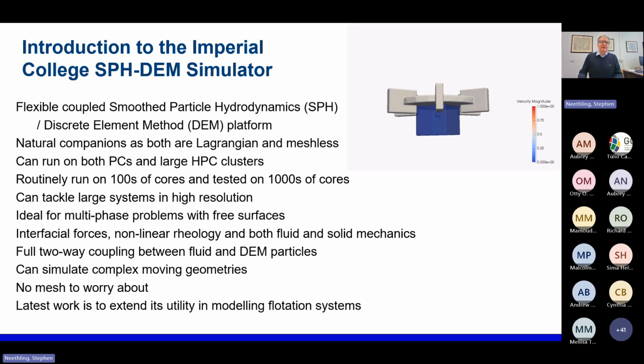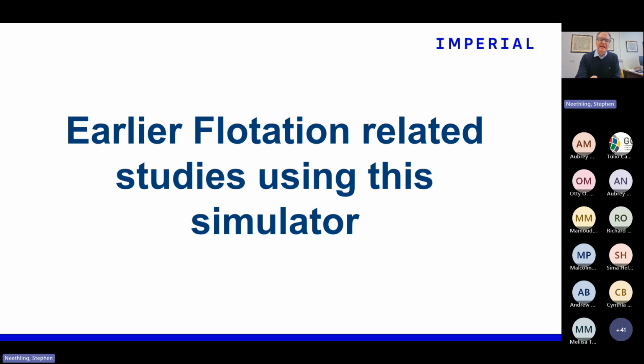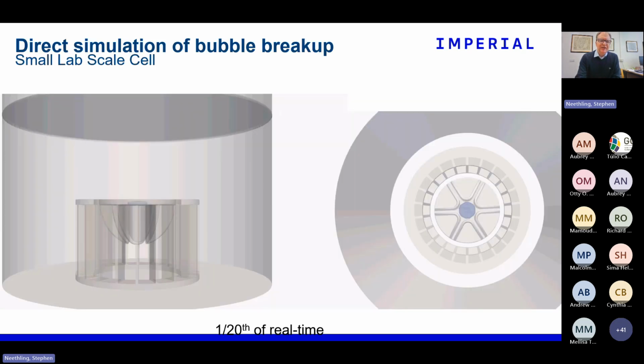This means we can tackle large multi-phase problems with free surfaces, including a lot of the rheology and behavior that you actually need to understand, not just flotation, but also a lot of other minerals processing problems. So I've done a reasonable amount of studies using this simulator. Some of the earliest ones I did were trying to understand things like bubble breakup around an impeller. So this is a very high resolution simulation, simulating directly, including surface tension, how bubbles break up around an impeller.